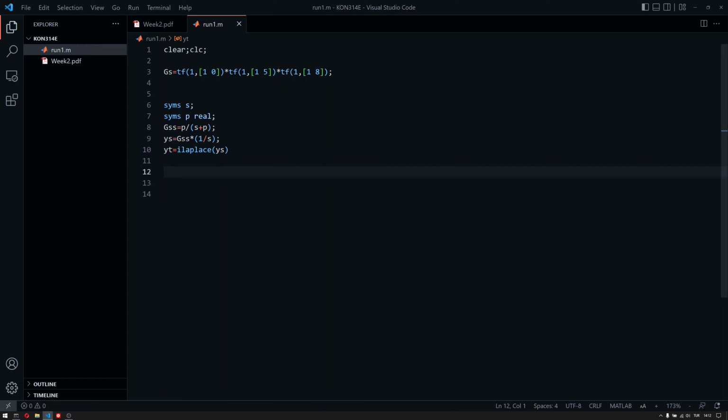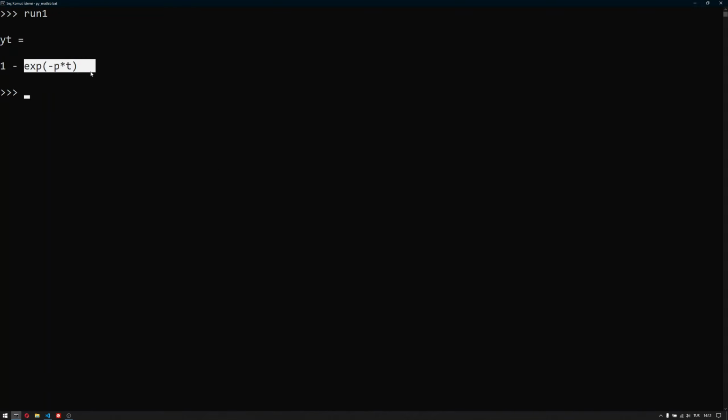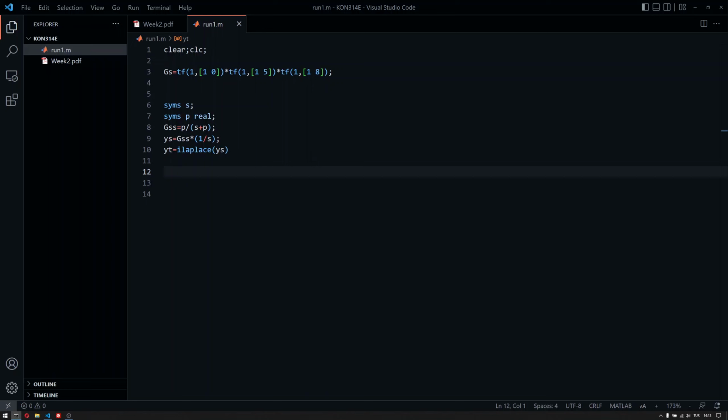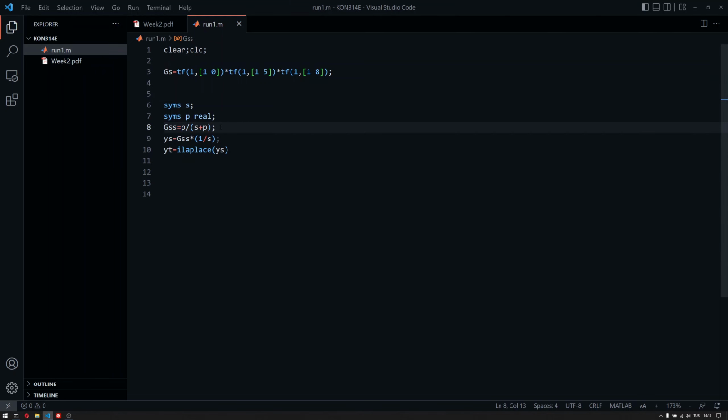We need some complex parts, imaginary parts, in order to have overshoot, because otherwise we get just exponential terms in the inverse Laplace transform. But if we have some imaginary values, then we will get sines and cosines. So that would mean that if we have a sine, that means frequency and that means oscillation, so we have overshoot. For that reason, we know that these type of systems, first order systems, do not overshoot.